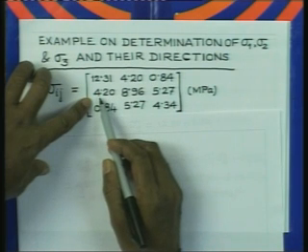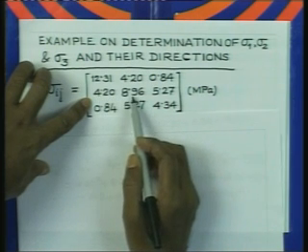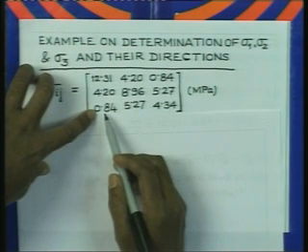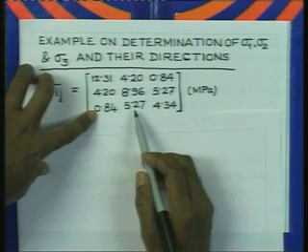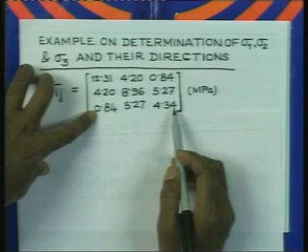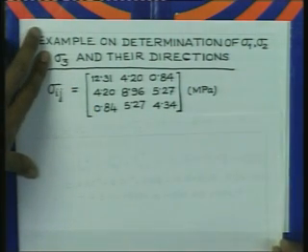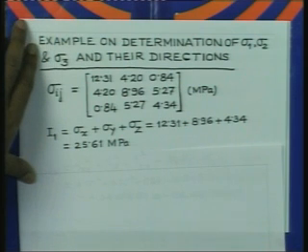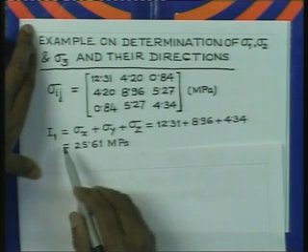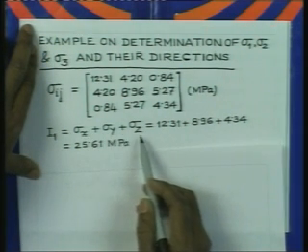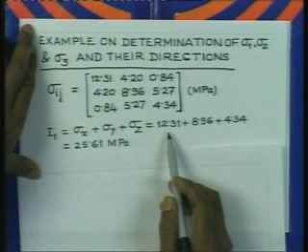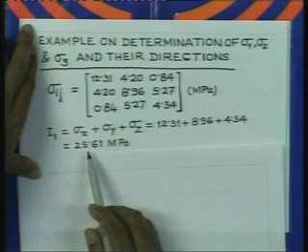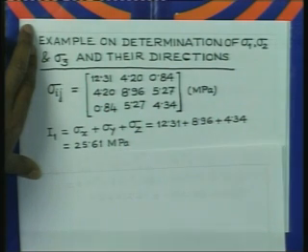Similarly, you have tau yx, sigma yy, tau yz, and this is tau xz, tau yz and sigma zz. Now, we calculate first the stress invariants using the data. I1 is sigma x plus sigma y plus sigma z. So, if you substitute the values, these 3 diagonal coefficients give you 25.61 megapascal.